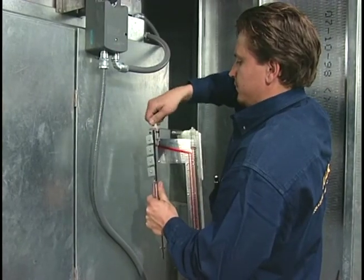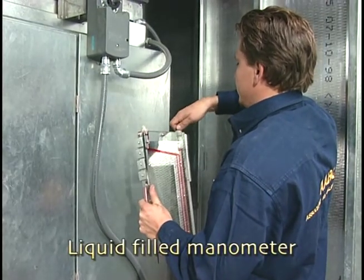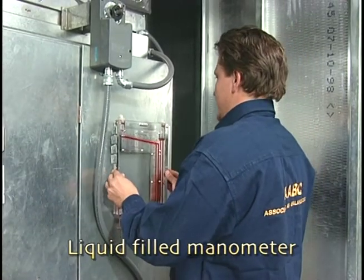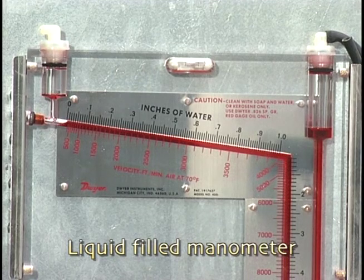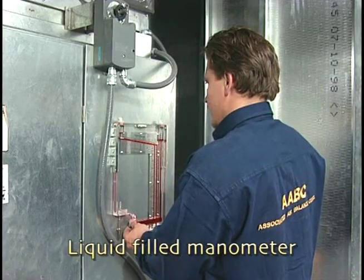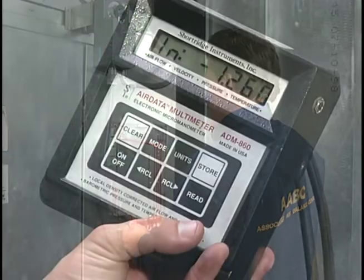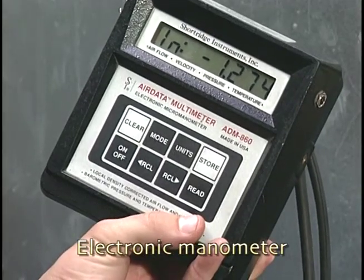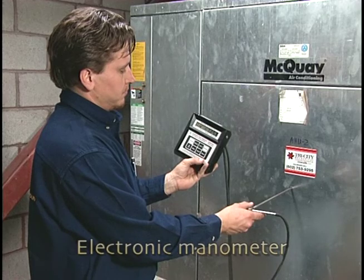At the unit, the TAB technician sets up the manometer. For a liquid-filled manometer, this will require leveling the instrument, opening both high and low ports, and adjusting the zero adjustment knob so that the bottom of the liquid, or meniscus, reads 0. Other than verifying calibration, installing or charging batteries, and turning on the meter, no setup is required for electronic manometers.